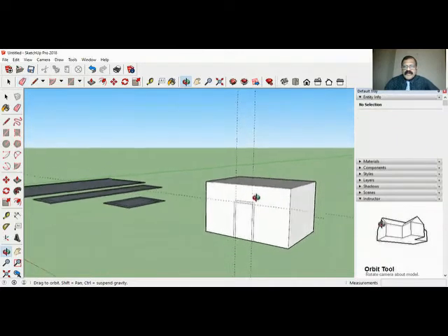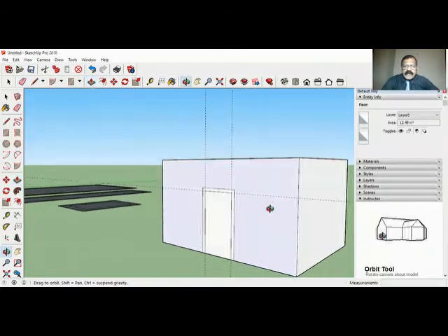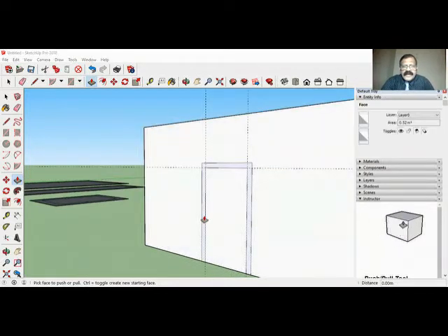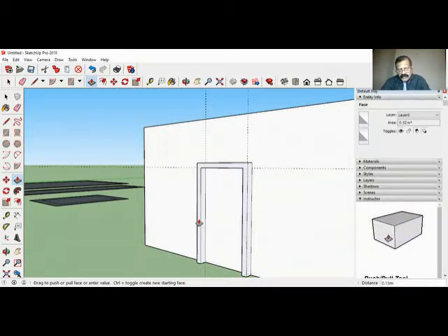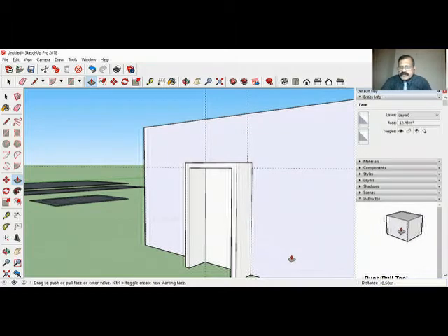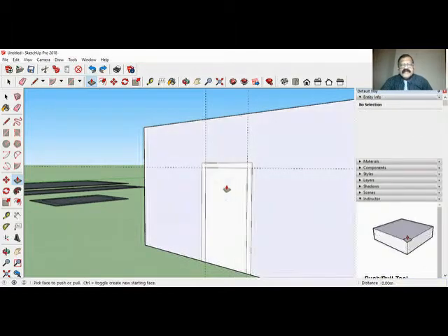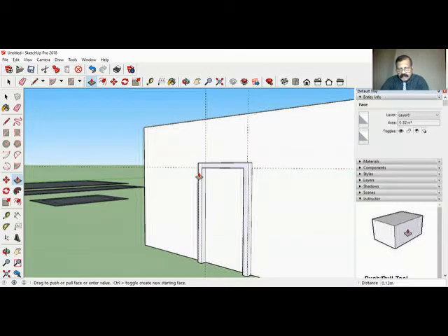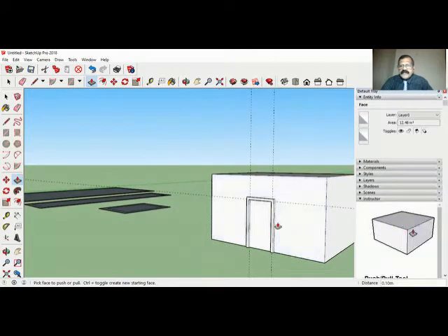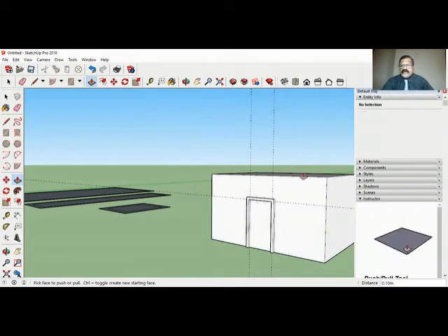So this offset command is very, very powerful. I'll go here and select the frame and bring little front and put some value, say 0.5. Oh, it's too much. You can undo this. 0.1. Okay. See, our door frame is ready. So same, you have used this guideline for this. I can draw window also other side.